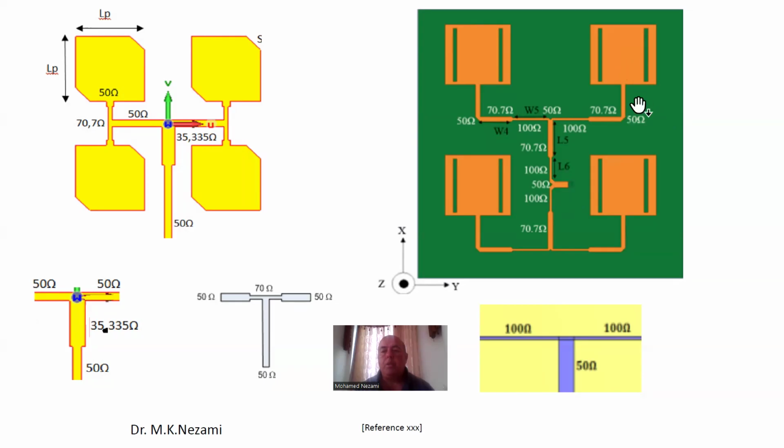Now the element itself is 50, okay? So what he does here is he uses this same splitter in here, again, to go from, let's see, he uses here 50 with 50, no, 200 ohms, and then he uses from 50 to 100, he uses a 70 ohm quarter wave line in here, okay?